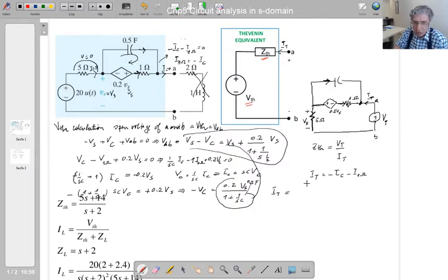what is the current of the capacitor? So consider now, this is node voltage here, if that's ground. So node voltage is Vx, isn't it? Vx, this node voltage, and this one is equal to Vt. Vx minus Vt over this impedance gives you the current of this impedance.